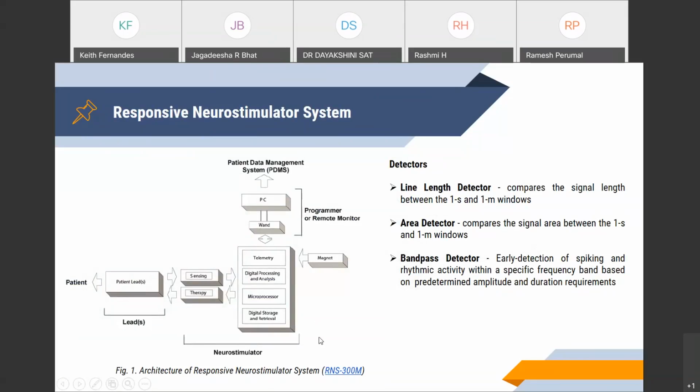I'm going to explain this because, as I already mentioned, the solution is very simple, but we should be very careful in selecting the right solution, and the right solution depends on the requirements and hardware platform. Depending on the target platform, you deploy the algorithm. So here I'm going to explain the target hardware platform. As seen from this figure, any closed loop DBS system is implemented using a microprocessor or microcontroller because the device has to be compact and low power. These two criteria are very important.